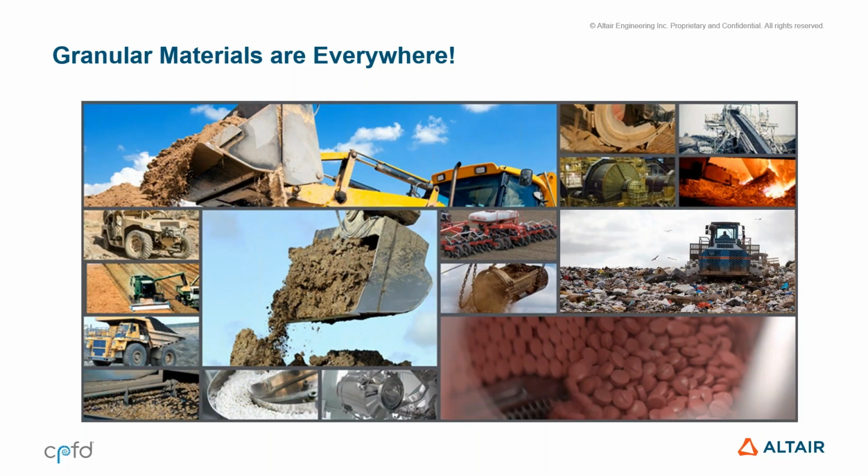The challenge is, though, that these materials are complex in their behavior. So, for example, if you consider an excavator going through sand, if that sand is dry, then it will behave more like a fluid. It will be very free-flowing, and an excavator bucket will likely pass through it very easily. However, if you get that same sand material wet, it will start to become cohesive and sticky with very different properties that will significantly affect the loads acting on the bucket and the surrounding equipment parts. This inherent variability is seen across industries for many material types and numerous different types of applications, and where understanding the behavior and influence of granular materials is vital to a successful design.